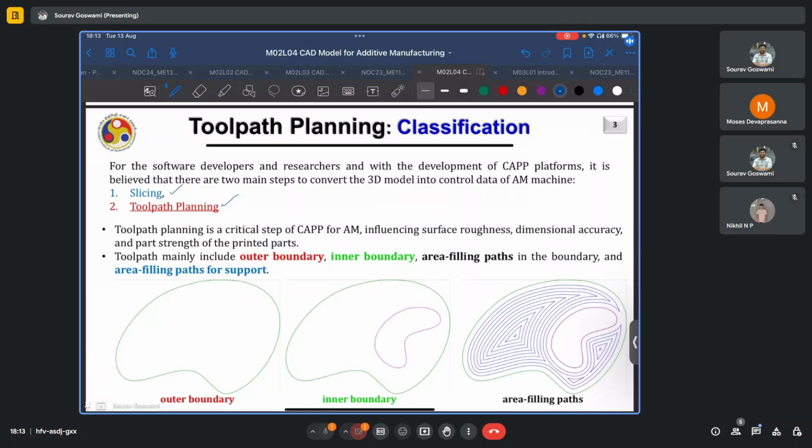Of course, the end product of any such process which you see is, say, if you're depositing a cube, for example, in each layer you will see something like 2 to 3 such perimeter passes, depending on how many you specify, and then some infill. So a typical raster infill would look something like this.